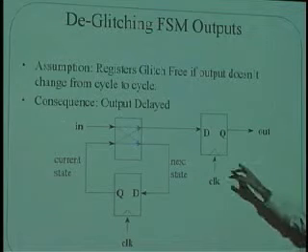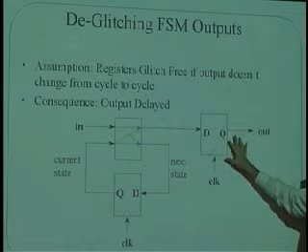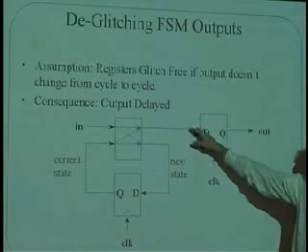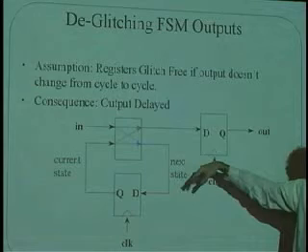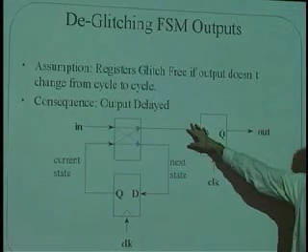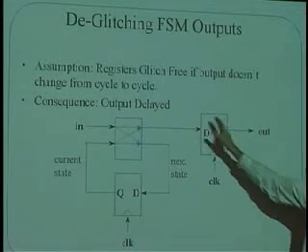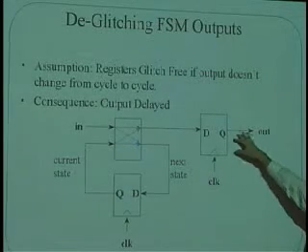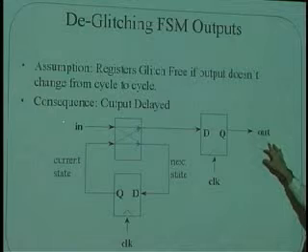And so how this thing solves the problem is if the old output had a certain value and then got contaminated and then got the same old value on it again, then when we take the picture of the new value that's coming out here, if it's the same as the old one, the output here will never change and you won't see the glitch at all.